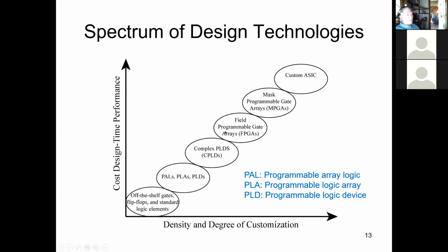The next step after FPGAs is where we take an existing piece of silicon that's already been mostly manufactured, but there's one step left. What's been manufactured is kind of like an FPGA. There's a whole bunch of gates or lookup tables or various things already pretty much created, and then all we're doing is creating the final layer to connect all these things together.